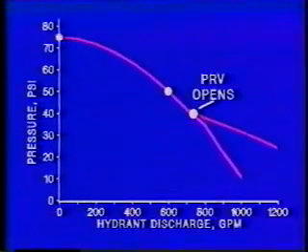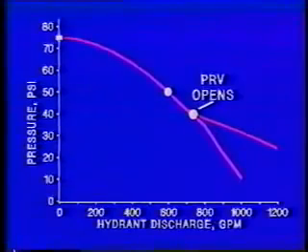If, for example, in this test we show you drop the pressure down to 50 psi during the test, you would tend to extrapolate those results and predict a flow of about 800 at 20 psi. However, if there's a PRV nearby and it opens at 40 psi, connecting the area you're testing with a higher pressure zone, you could possibly get significantly more water during an actual fire due to the action of the PRV. So you need to be aware of when a pressure reducing valve could influence the results of your tests.